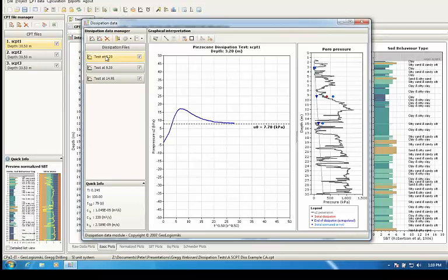Next question: what is the role of strain path modeling of CPT behavior? I'm not quite sure what that question means, but certainly as the theories get more comprehensive, as people are doing more detailed finite element analysis using more comprehensive constitutive models, people are getting a better handle on the initial pore pressure distribution and therefore the dissipation test.